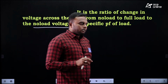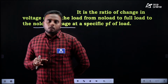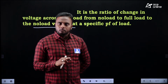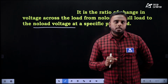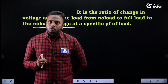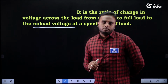Generally, let the transformer secondary voltage be 200 volts. The secondary induced EMF is 200. And how much voltage will appear at the load whenever we connect a load? Will more than 200 appear, or less than 200, or equal to 200? Definitely it may be less, it may be more, or it may be equal. That depends on the load power factor we connect. So it is not the same every time.